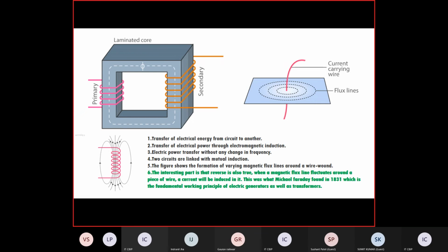As the conductor supports the flow of current, the ferromagnetic material supports the flow of flux. And the flux, like a current, flows in the core and links to the secondary winding. Because the input applied to the primary is alternating current, the flux is also alternating. If the current is sinusoidal, the flux will also be sinusoidal.